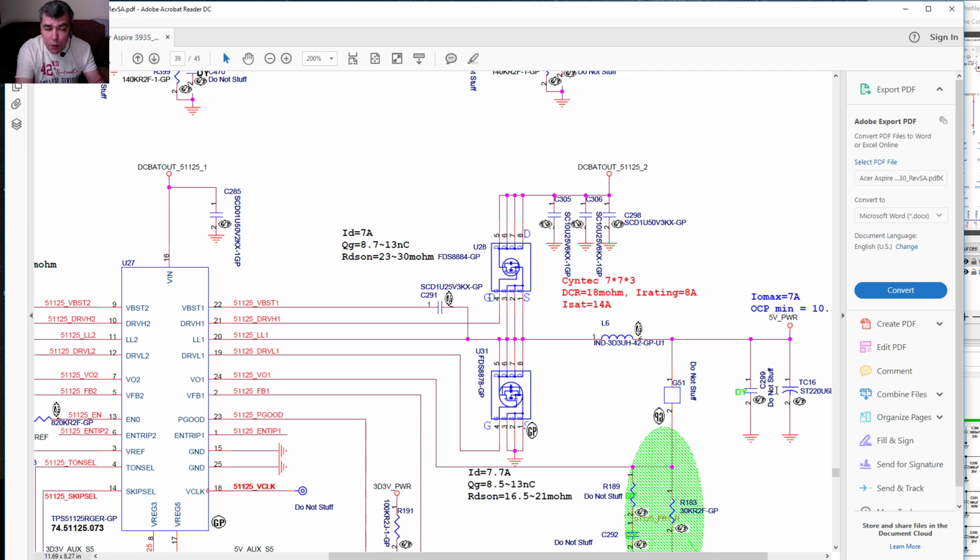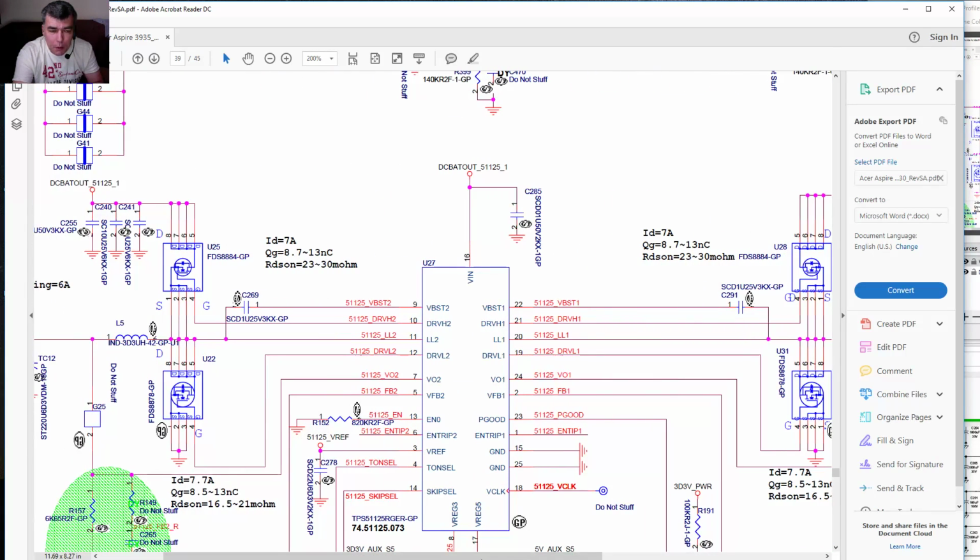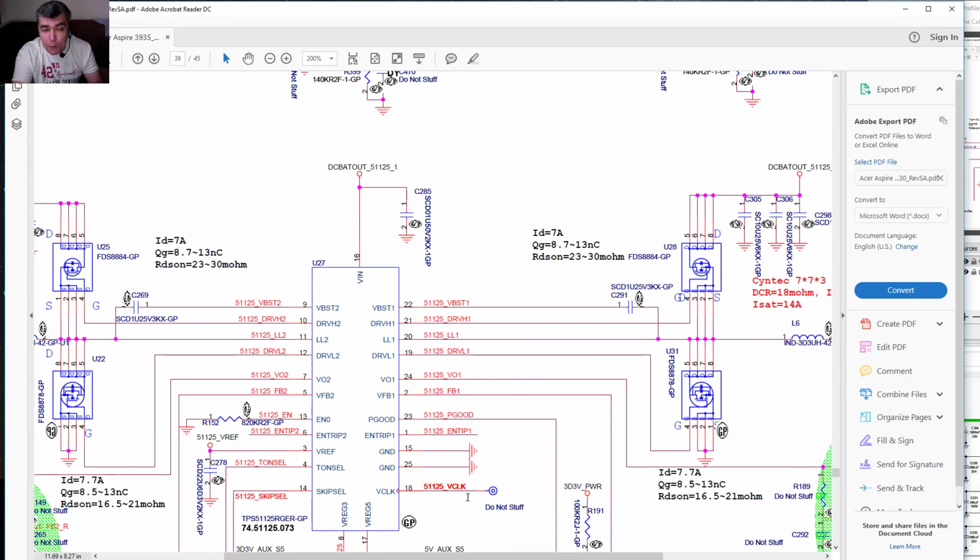You can have a short MOSFET, or a short capacitor. I found a lot of short capacitors and short MOSFETs. There's no point speaking about some random resistor, because it will not get burned. I also found the MOSFET controller chip burned.